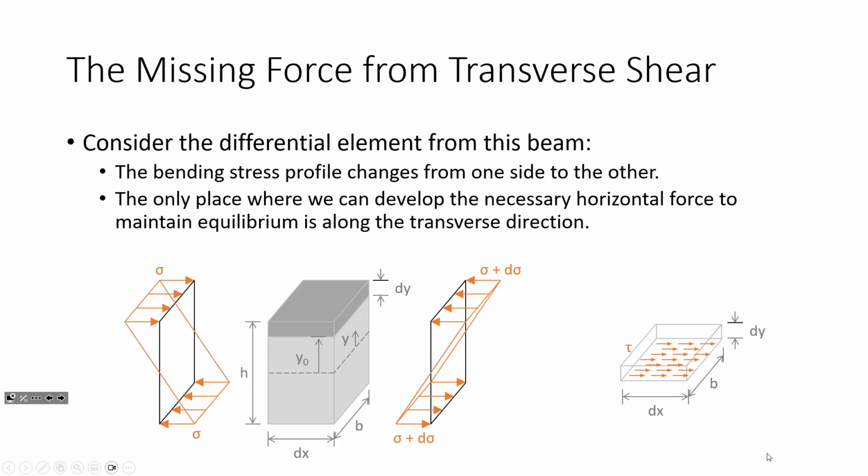And I propose that what's got to happen is we have to develop these transverse shears between the plies. It's like what's going on here, right? The reason that it's so easy to bend this is because the pages freely slide across one another. Once the pages are adhered together and they can't slide across one another, that's when I start to get my increased stiffness. So as I bend this, there is a transverse shear that is developed between those plies, okay? That's what transverse shear is all about, and you need that force in order to maintain equilibrium of the beam, okay?